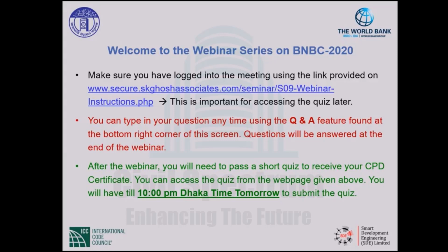Thank you. That is a very important piece of information. Yes, deformation compatibility must be ensured. What is the difference between story drift and seismic drift? Story drift is the inter-story drift, that is the amount of deformation per unit height between two stories. The story drift can be because of wind load, but when we consider story drift because of earthquake load, then we call it seismic drift. I hope I have answered the question.